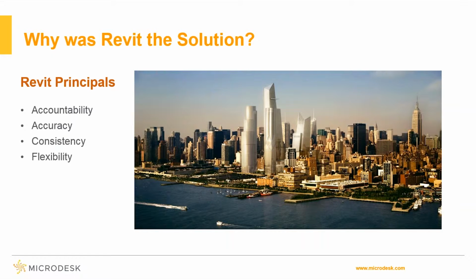When we get into the accuracy, in a little bit, we're going to look at the elevators and the way that they were created. And they were created as a smart family, so that once the family was created and the schedule was set up properly, you would now just have the task of placing the elevators into the model, then operating a self-populating schedule so that you, at any click in time, would know exactly how many elevators were in fact in the model, as well as every specification that was needed either on the architecture side or the client side to be used.